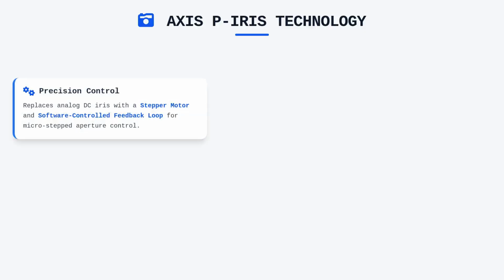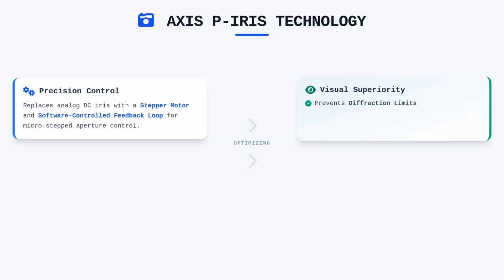This is where Axis proprietary P-iris technology fundamentally changes the equation by introducing a stepper motor and a sophisticated software-controlled feedback loop. Unlike the analog nature of DC iris, P-iris allows the camera to exercise exact, micro-step control over the physical aperture opening. The camera software constantly calculates the optimal iris position based on both the light intensity and the lens characteristics, ensuring that the aperture is never restricted to a point where diffraction ruins the image quality.